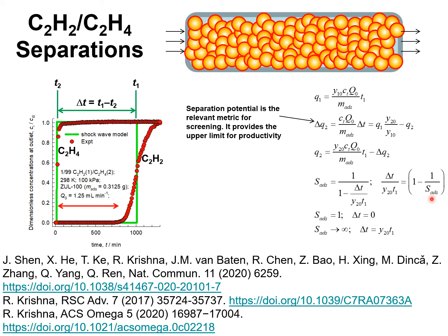Let's take a limiting case where the adsorption selectivity is unity. In other words, the adsorbent is non-selective. Then both components will break through at the same time, and delta T is 0, and that can be easily derived from this expression. So the Shockwave model is useful to ascribe a physical significance to the adsorption selectivity as it relates to breakthroughs in a fixed bed adsorber.